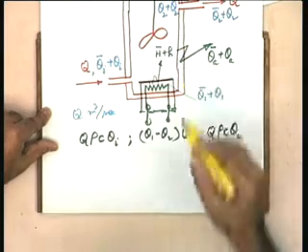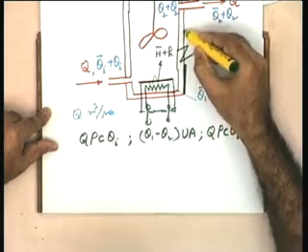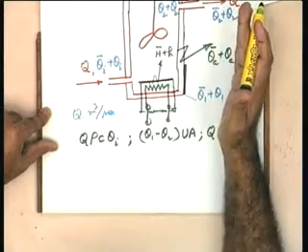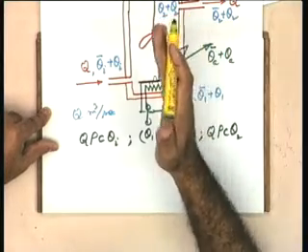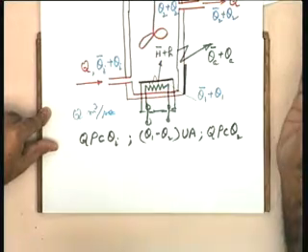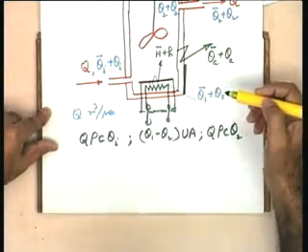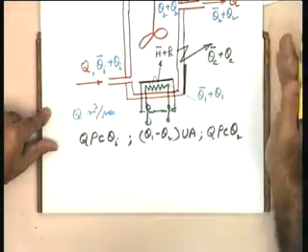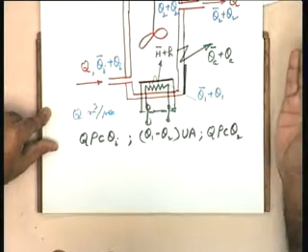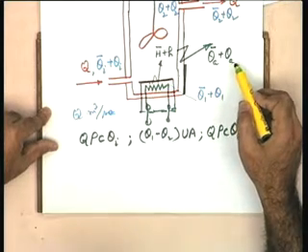If that is the case, then because of this particular interface between the solid mass of the tank wall and the fluid which is the air, again I may say that through the convective process the heat flow is taking place from the tank wall to the environment. It is the convective process, because the tank wall gives you the fluid solid interface, and U the film coefficient for that will come, A the area of cross section will come, and therefore, between theta 2 and theta A there will be a flow of heat.